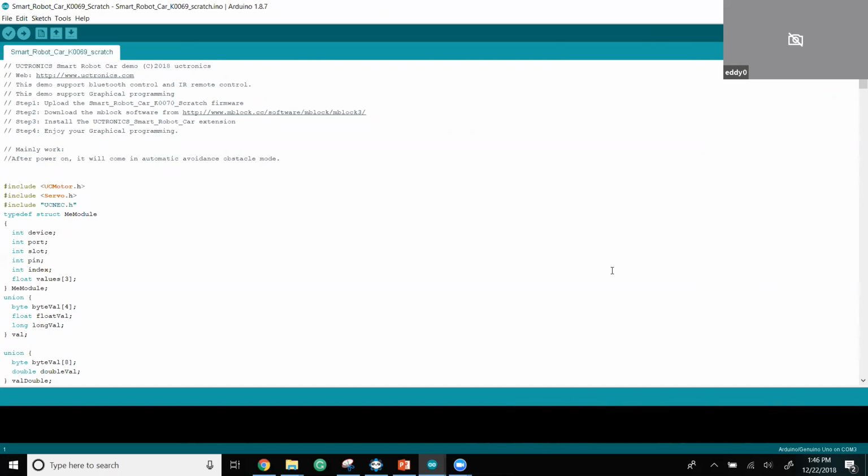Let's see, any other? Sometimes your Arduino board has all these pins in it, right? Make sure those pins are always seated correctly and that you're not seeing things kind of pull away from the board itself. That would be bad. Sometimes you can just push those back in. Make sure things aren't bending at any angles. If you were to unplug one of your sets of pins and put it back in, always make sure that you put it back in the correct way.